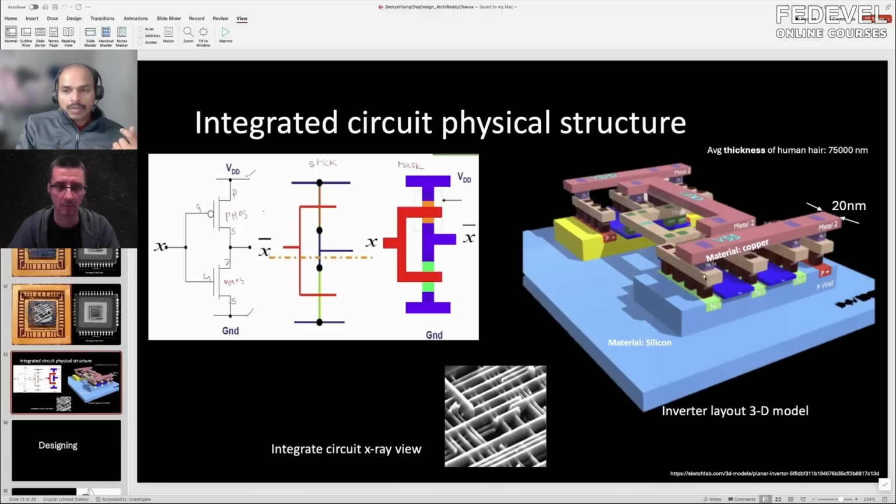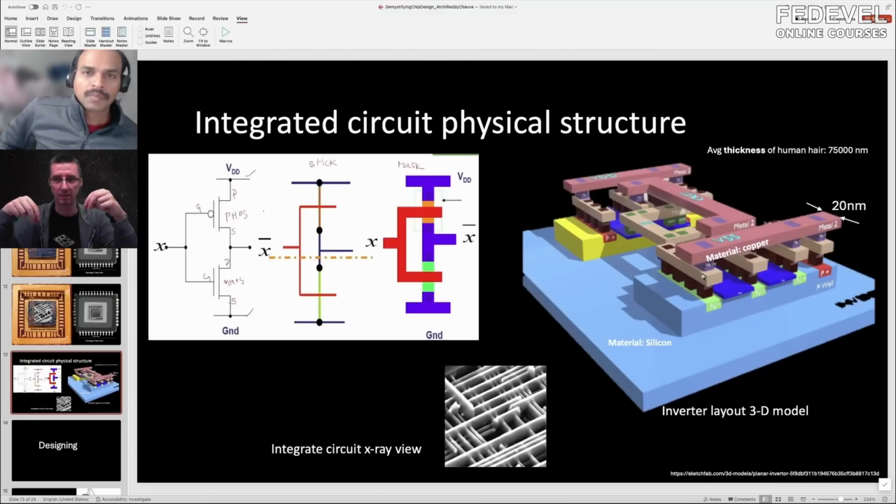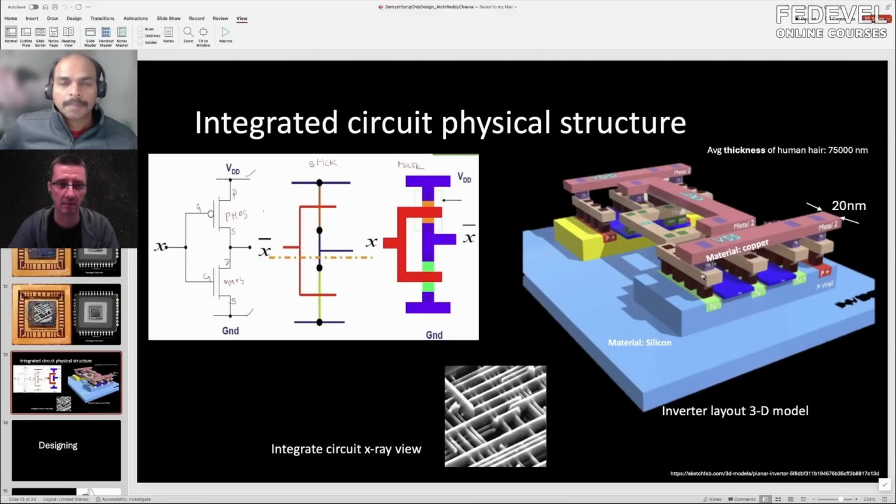Now, I go up to where the metal layers are. Before we continue, you cover the whole layer with some kind of isolation, which makes isolation between different layers, and you only make holes where you would like to have contacts going up. We fill in the material and then we polish it, then put another layer of mask, again fill in material and then polish. So that's what we do. We build layer by layer, level by level.